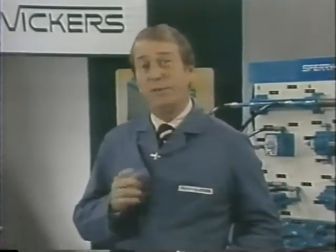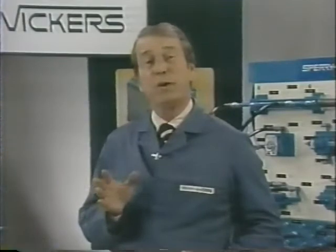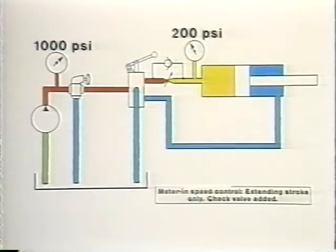Assuming a workload of 2,000 pounds and an area of 10 square inches, the pressure on the cylinder side of our orifice is 200 psi. We learned earlier that we must have a pressure difference across an opening to cause flow through it. And in this case, with pressures of 1,000 and 200 psi, we have an 800 psi pressure difference.